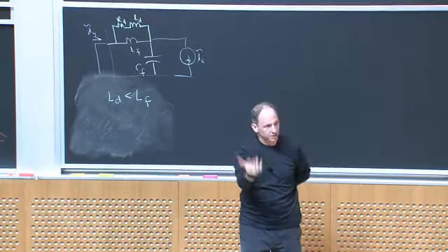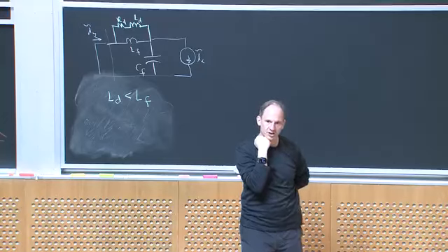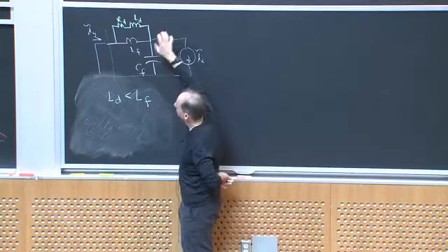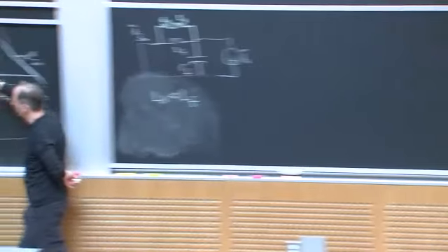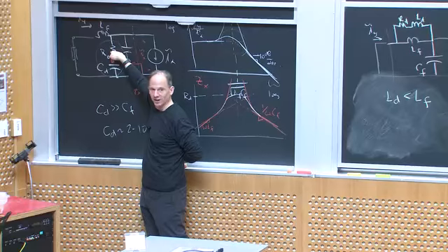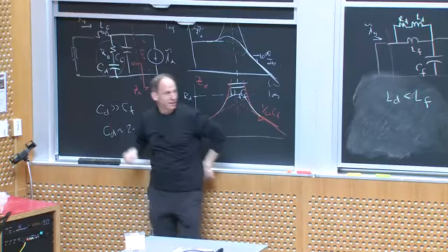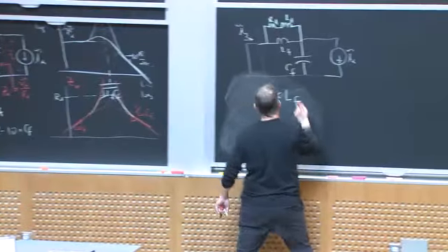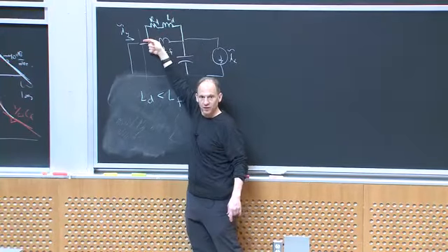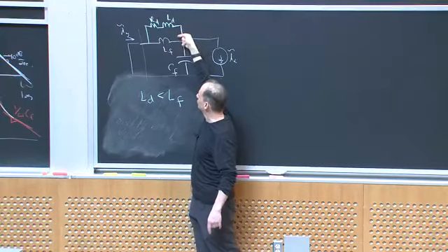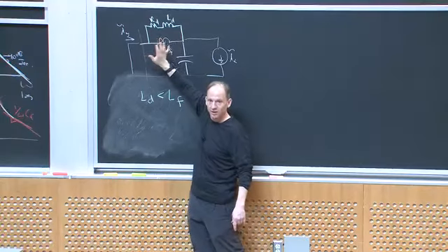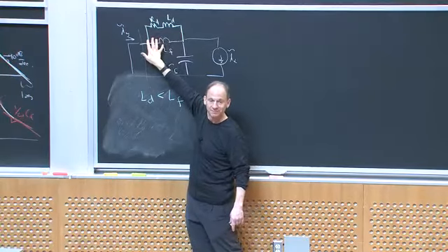The downside to this filter damping strategy is that, whereas this additional shunt path only improved your filtering well above cutoff, here, because LD is small, you're hurting your filter impedance, right? This path's impedance has gone down compared to this path's impedance. So this doesn't do as good a job slightly above cutoff, okay?